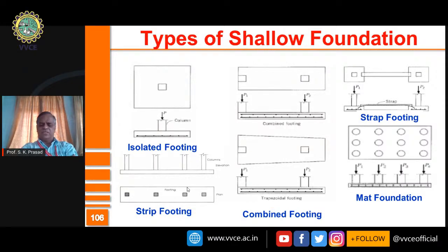As I mentioned, the simplest one is isolated footing. Naturally, given a choice, we should go for it because it is economical and easy to construct. You don't require much time. You don't require sophisticated equipment. Even design is easy.